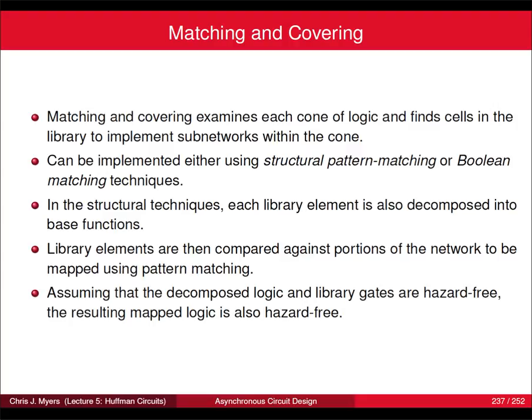So in the structural techniques, each library element gets decomposed into base functions the same way that we decomposed the function we're trying to implement. Then the library elements are compared against portions of the network, doing pattern matching. And then assuming the decomposed logic and library gates are hazard-free, the resulting mapped logic will also be hazard-free.